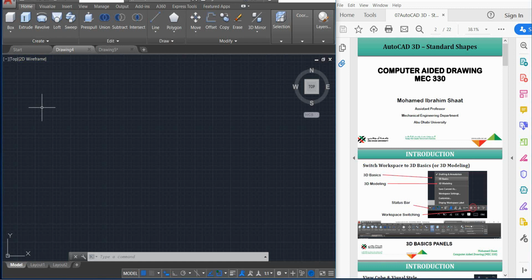So how can we build 3D solids or models using any software? It is not necessarily AutoCAD. Using AutoCAD, SolidWorks, even 3D Max, it works with the same concept: we have to start with a two-dimensional sketch, then we use one of these creation commands to convert it. These commands are not building a 3D solid. These commands are converting a two-dimensional sketch into a 3D solid.